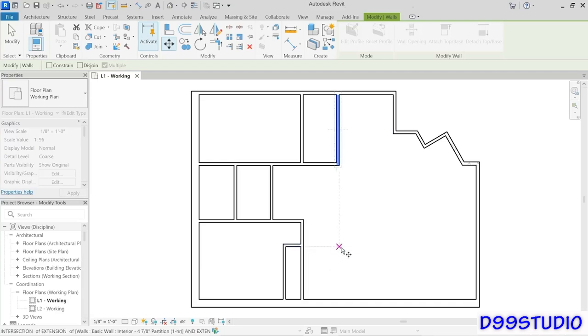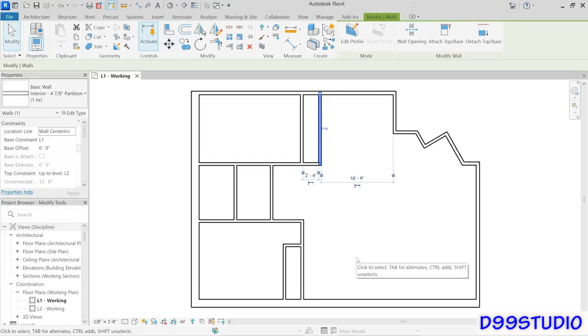So let's say that I wanted to move this wall a distance that was equal to the width of this closet. So I could snap right to this endpoint right here, kind of drag over to this endpoint here and click again. And notice that it moves that wall. And of course, because it was connected to another wall, that other wall stays connected. Now that makes for a really narrow space there to the left. So perhaps I moved that a little bit too far.